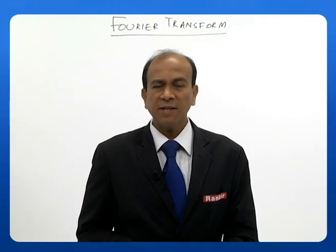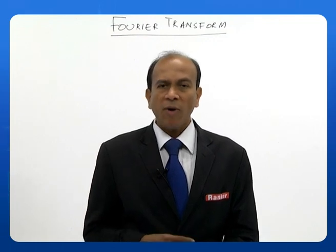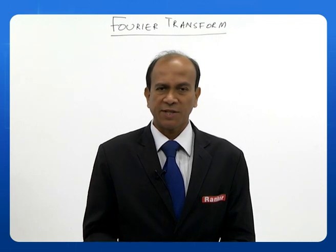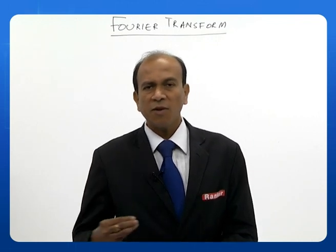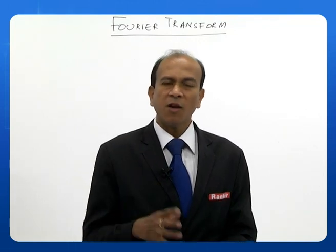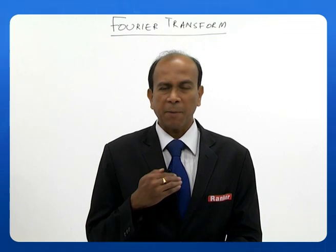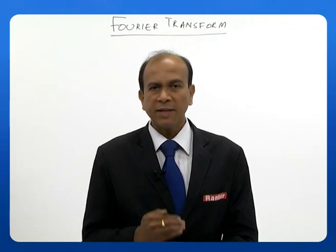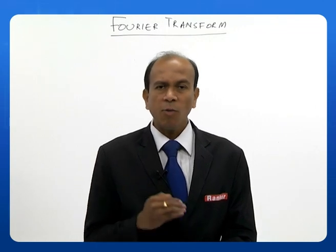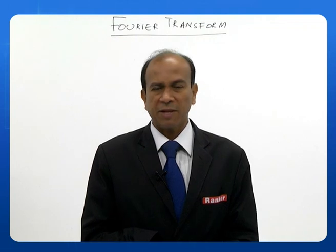So what is it we have done here? We are trying to find out the average power of a signal. The signal can be either a current signal or a voltage signal, etc. So what is the current flowing in a 1 ohm resistor? What is the voltage drop across a 1 ohm resistor? That is how we find the average power. That average power is given by P is equal to limit t tends to infinity 1 by T integral minus T by 2 to plus T by 2 of mod g of t whole square dt. This is the power. This is called Parseval's power theorem.